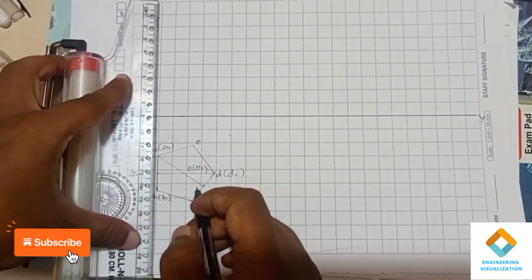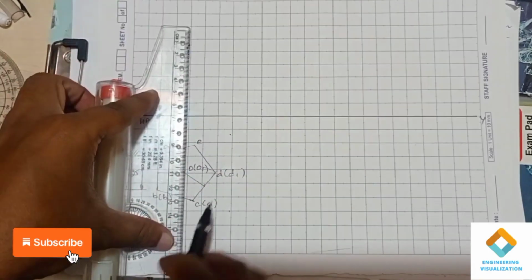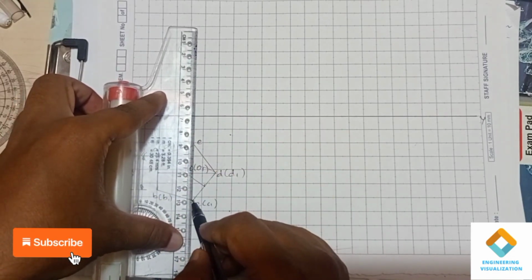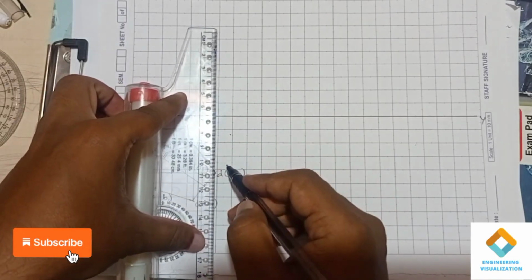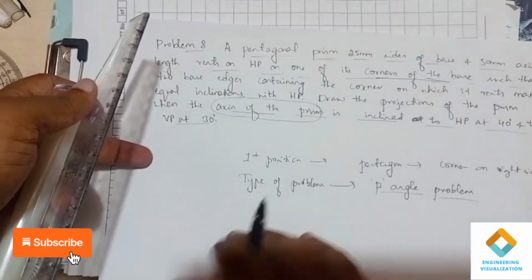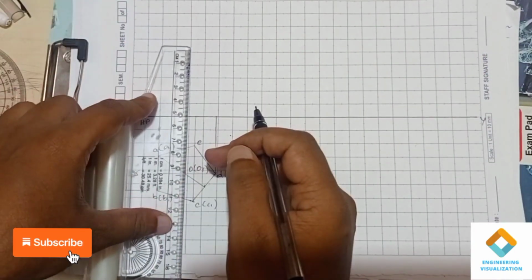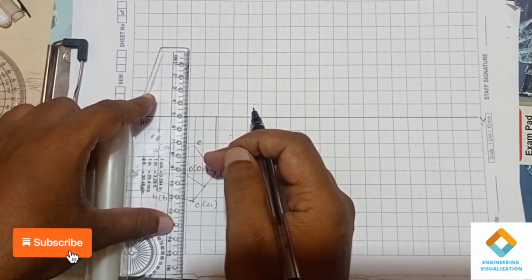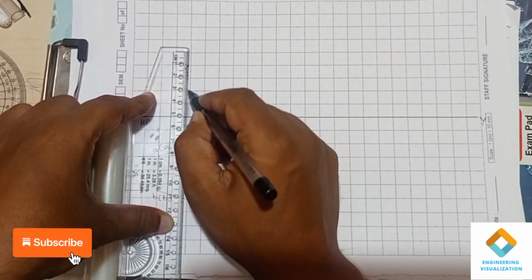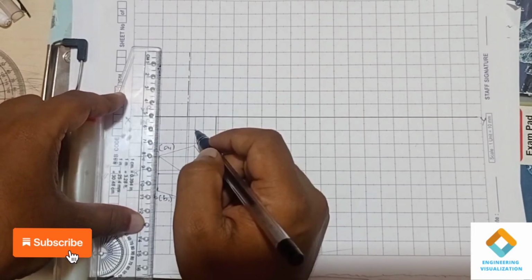Now draw the projection lines to construct the front view here. Projection lines should be thin lines, so make sure you draw thin lines. In the problem the axis is given as 50 mm. The front view of the prism is a rectangular face. So first I will construct the axis for a dimension of 50 mm. Same way you can draw vertical lines for a length of 50 mm.